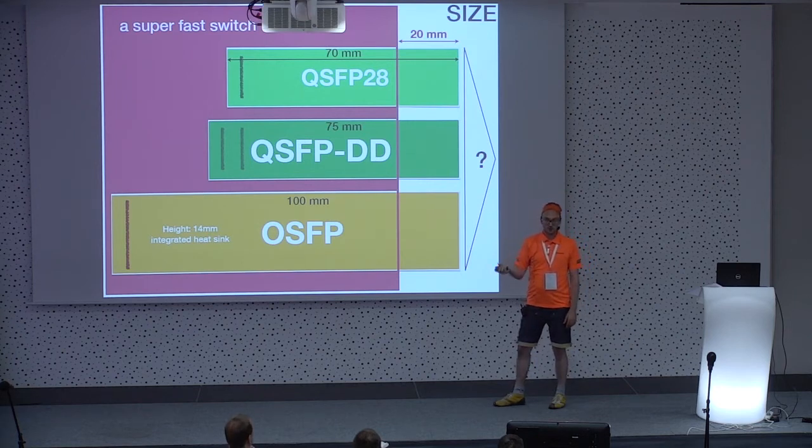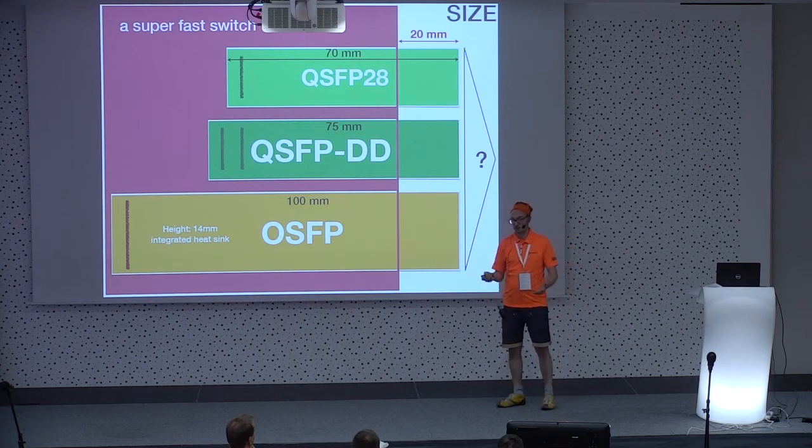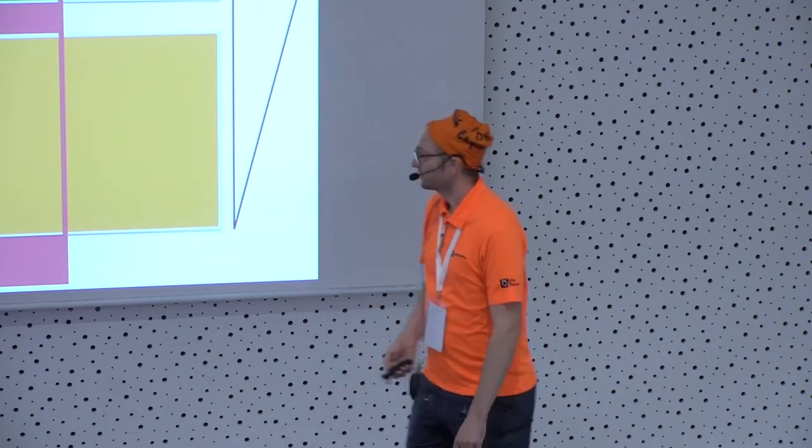So taking 20 millimeters just for the transceivers, at least 50 millimeters for your fiber optic plugs, plus maybe a little bit of bend radius for your fiber optic patch cable. This would be helpful to getting the light through the patch cord. You will end up needing at least 100 millimeters of space from the first rack unit to your front door. Not only because of the cabling, but also, as we will see at the end about the power dissipation, you need that, I'm pretty sure, to get rid of the heat generated by the entire system.